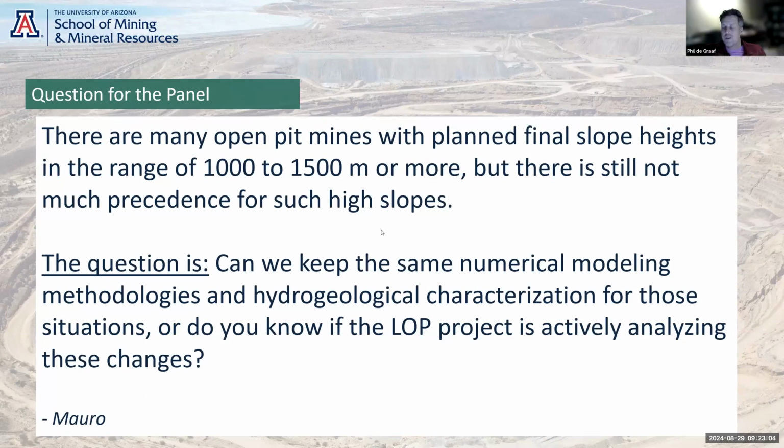I think that significant change in consequence with these very high slopes is a complete change in mindset about managing and then designing as well. So in terms of the numerical modeling methodologies, certainly from a geotechnical stability model perspective, you'd be running several different types of model and making sure that you could capture the right mode of instability with those larger slopes.